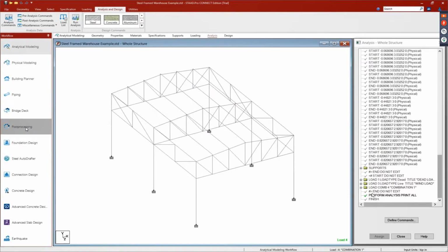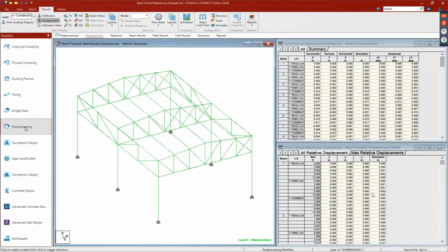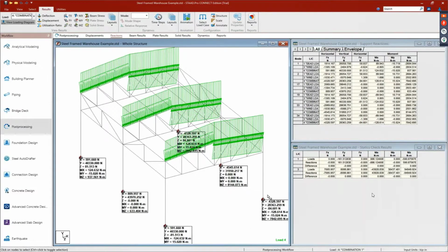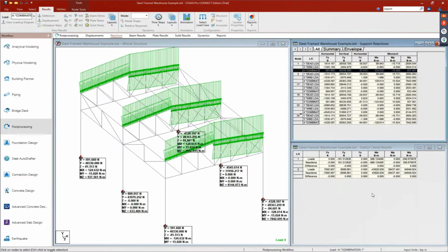So you may now go into the tab where you will see the different load reactions and load combinations that you will use with the design of your connection. You may select the governing load that you will use with your design of connection. We will at least select three governing load combinations.